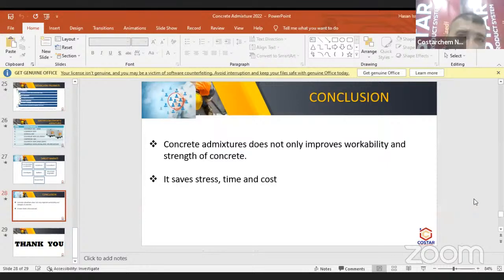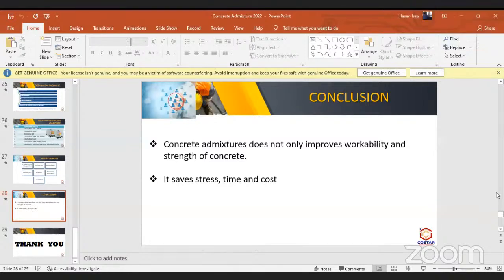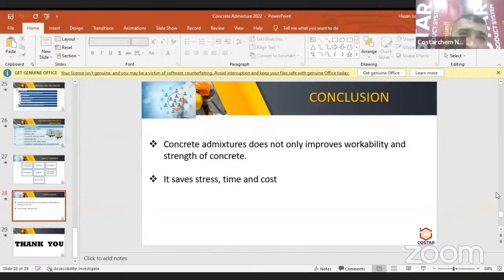The most important thing is that we avoid water going out from the concrete for no reason. The evaporation of the water and the water progressing from under should be at a certain rate. If not, cracks will happen, shrinkage will happen, and the durability factor of your concrete will be lost. Remember, curing equals 50% of the strength of your concrete, and if it equals 50% of your compressive strength, it means it equals more than 50% of your durability factor.